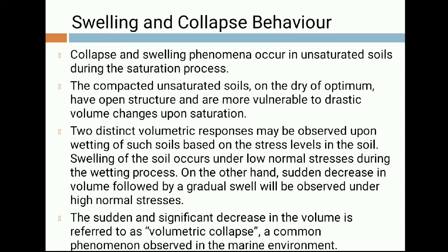Now let us see what are the swelling and collapse behavior of a black cotton soil. Collapse and swelling phenomena occur in unsaturated soil during the saturation process. That is, the soils which are unsaturated have voids which are not filled by water. If they are filled by water because of some means, the possibility of swelling will be more. The compacted unsaturated soil on the dry of optimum have open structure and are more vulnerable to drastic volume change upon saturation.